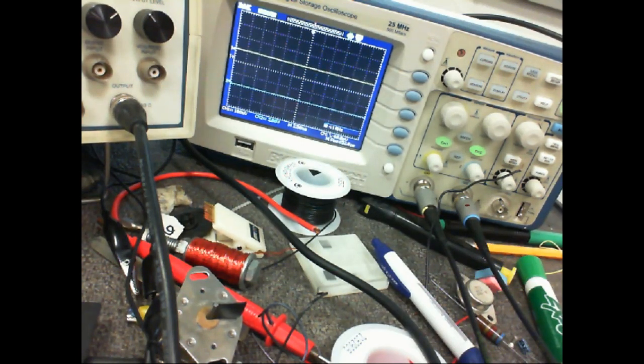But in signal wires, we're dealing with high impedance loads or high resistance loads, because we're not trying to send power, we're trying to send signals. So the circuits are high impedance, and these are the ones we have to really worry about for EMI. Fiber optics, no such thing, because it's electromagnetic induction. Light doesn't care. So one thing nice about fiber optics is they are impervious to electromagnetic interference.